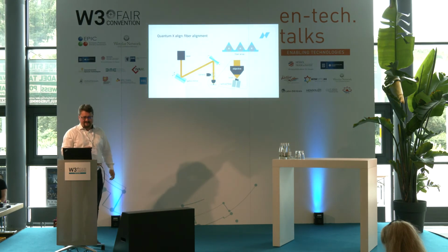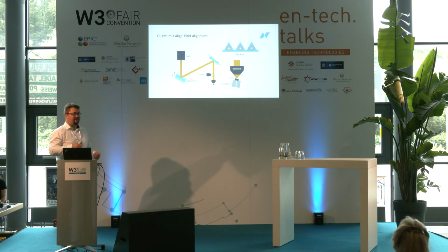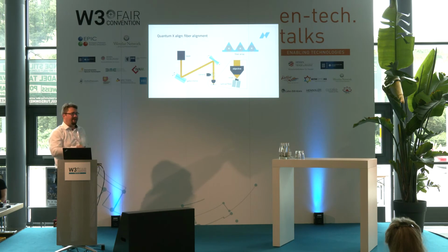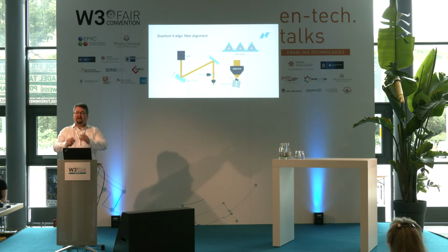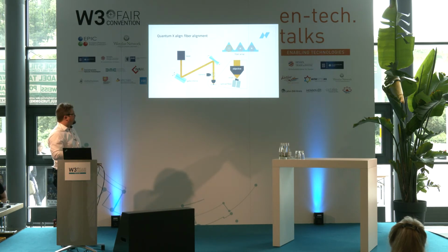And with the Quantum X Align, we can now use an integrated camera to detect these fibers in the field of view of the microscope objective. And actually we're using a backside alignment so that the core of the fiber, which is not always exactly in the same place, is illuminated, and we can detect exactly where the core of the fiber is, and then we can print in place.